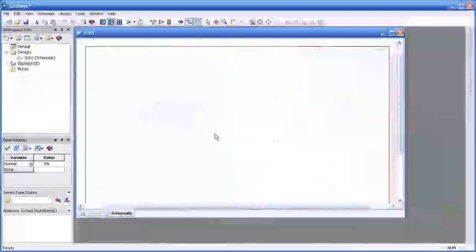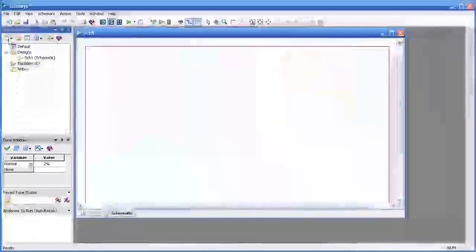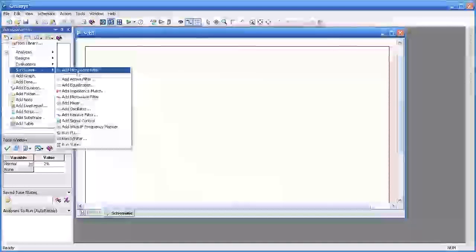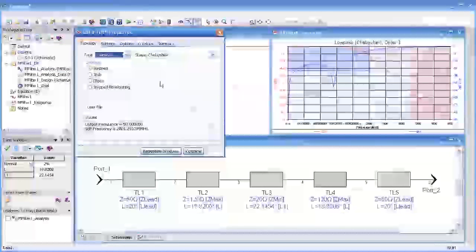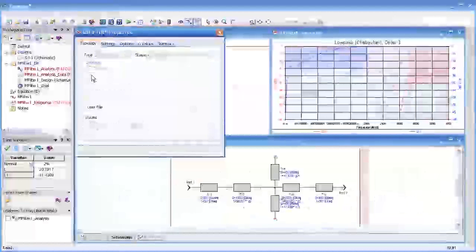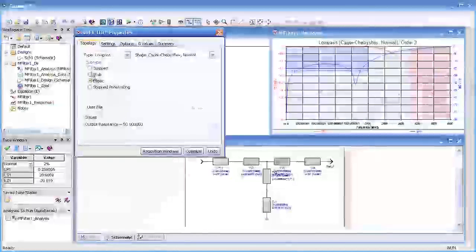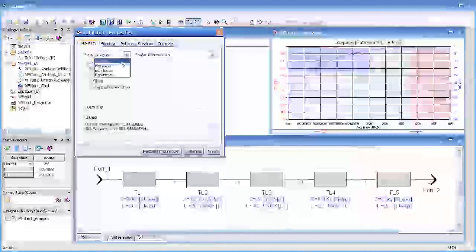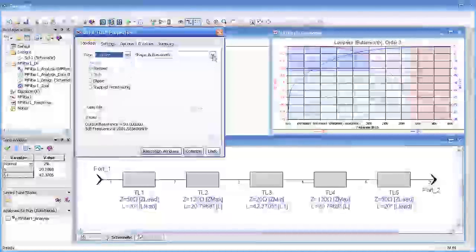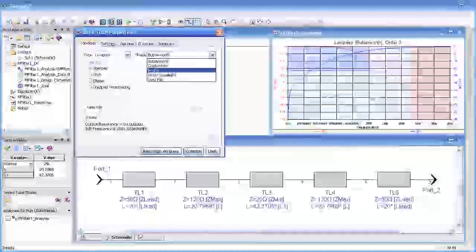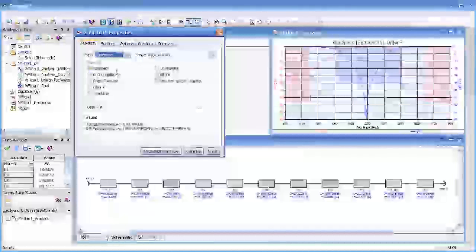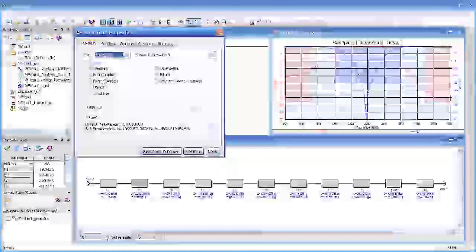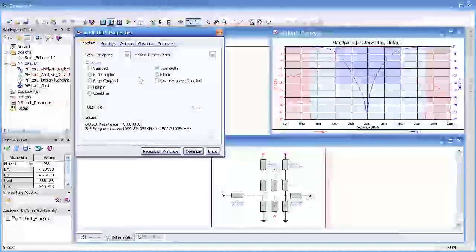Okay, next I'd like to show you how we start and use M filter. From the workspace tree, we'll select synthesis, then add microwave filter. In this case, I'm going to select the factory default, which turns out to be a low-pass step filter. And as I step through these, you can see the various configurations. We can select low-pass, high-pass, band-pass, and so forth, just like in the passive case. And there's different shape factors. I'm going to select the band-pass for this example, Butterworth, and not a step or one of these others. I'm going to select the interdigital for our example.